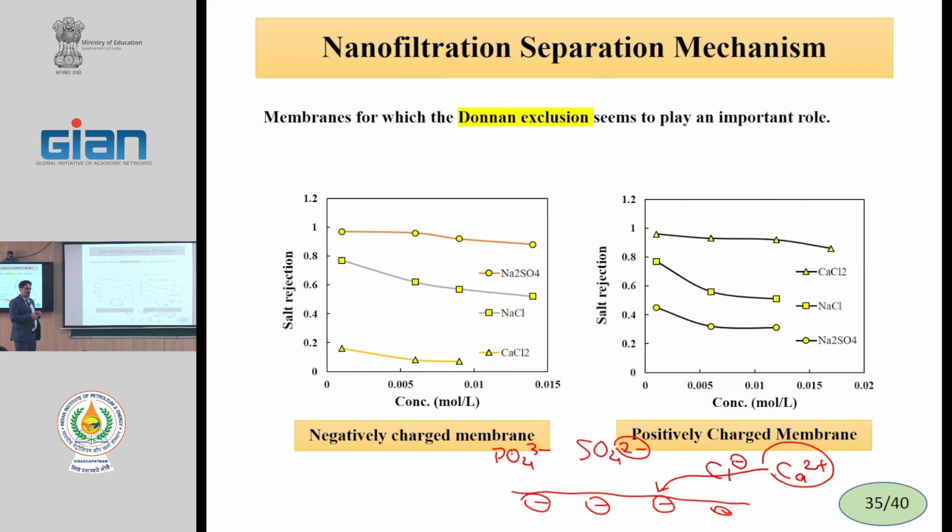Separation of lithium from magnesium is very important for the production of batteries. The lithium rejection is lower than sodium because lithium is smaller. To increase lithium selectivity, we must use non-porous membranes, usually TFC membranes, and nanofiltration is not suitable for lithium.